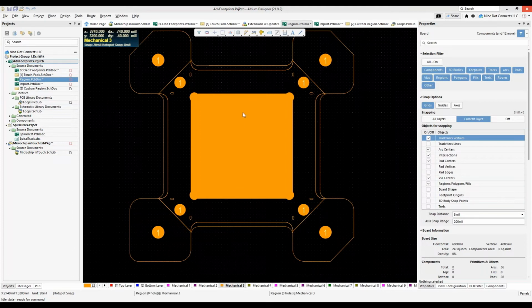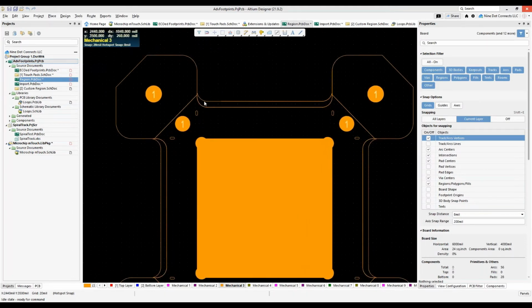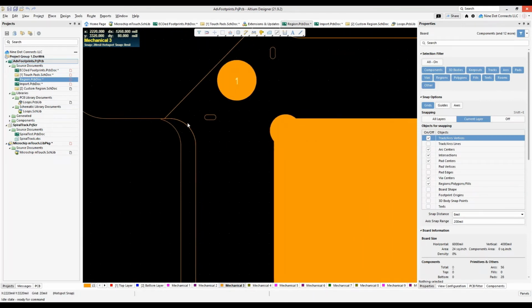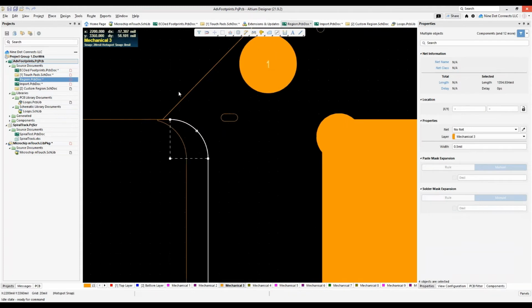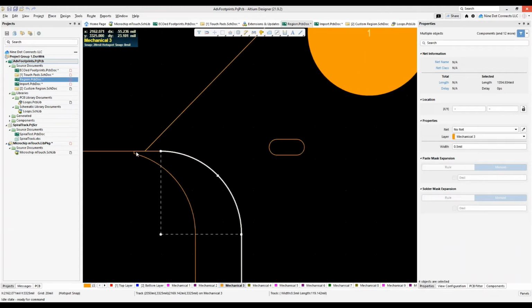Okay. So now that I've got this over here, I need to select the outside perimeter here. And this would probably take me about 3 to 5 minutes, and I don't want to waste your time doing it. But in order for me to create the outer perimeter for the polygon pour that I'm going to do, that's what I would have to do. So you would just have to hold down your Shift key and go, either right to left or left to right, to get each one of these things. And you want to make sure that you get all of these, okay?